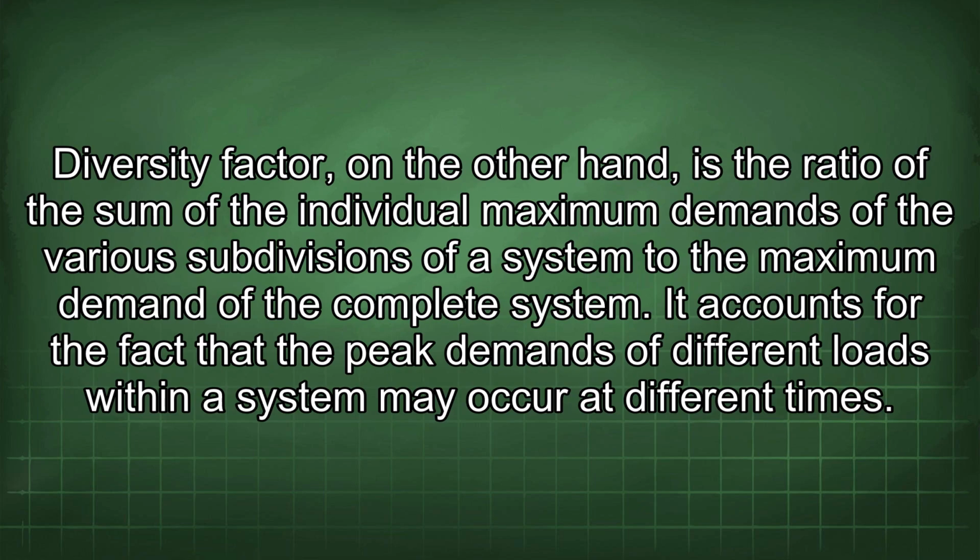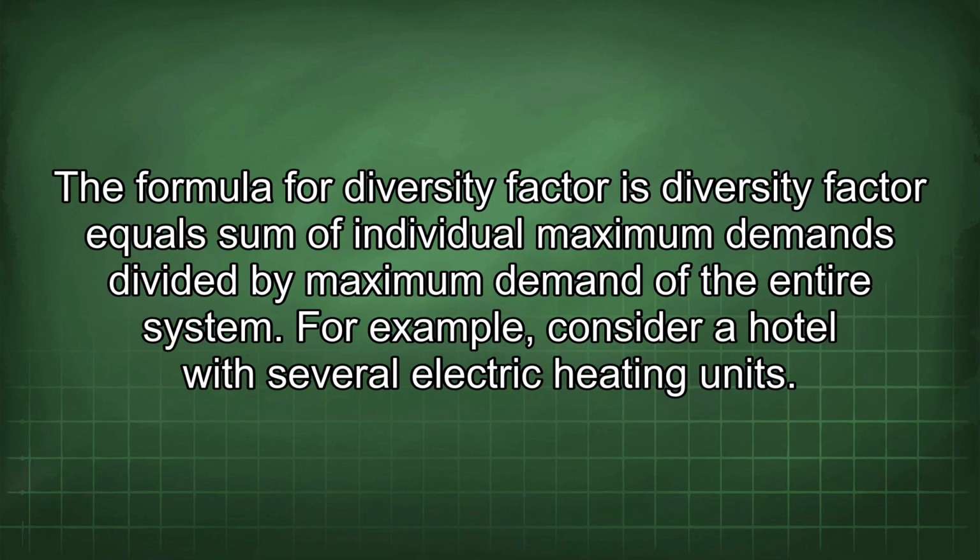Diversity factor, on the other hand, is the ratio of the sum of the individual maximum demands of the various subdivisions of a system to the maximum demand of the complete system. It accounts for the fact that the peak demands of different loads within a system may occur at different times. The formula for diversity factor is diversity factor equals sum of individual maximum demands divided by maximum demand of the entire system. For example, consider a hotel with several electric heating units.